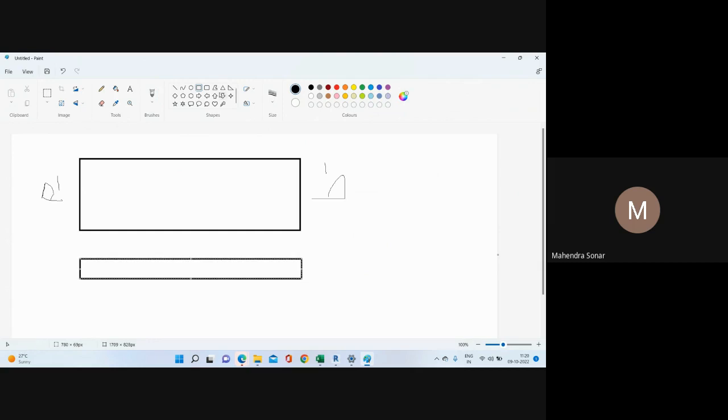And just consider this is a 300 thick slab. Just consider the soil condition here is very loose. For stability purposes we need to add some edge beam here, like that along all the periphery.